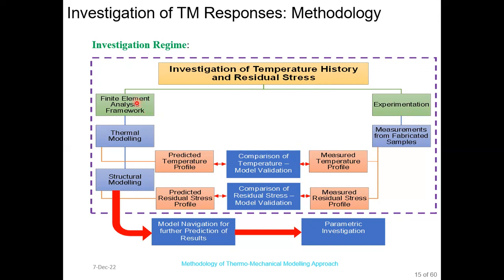So based on the FE-based thermomechanical modeling, first I have performed the thermal modeling, and after that I have performed the structural modeling, utilizing the predicted time-temperature history from the thermal model as an input to the structural model. After solving the structural model, I have got the residual stress profile.